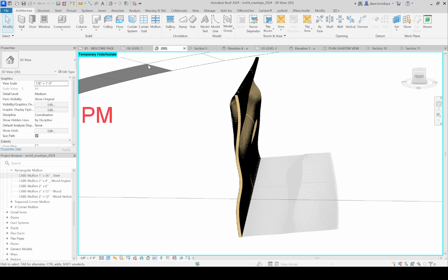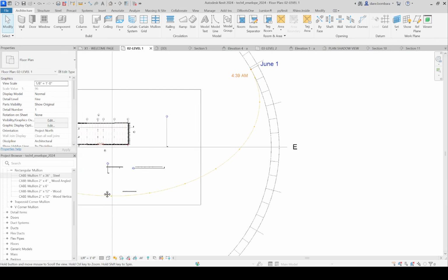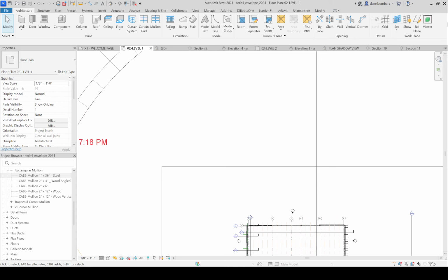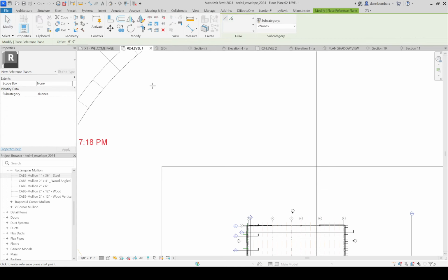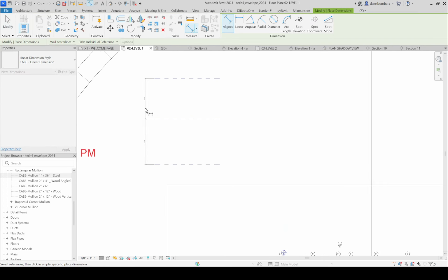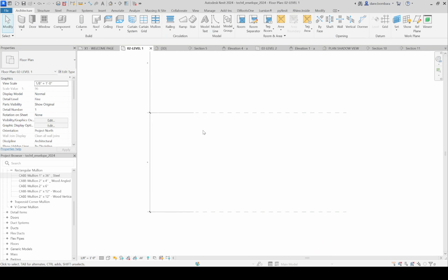So what I did here to make something like this is I'll do a very simplistic version. We talked a little bit about reference planes last week. I made some reference planes that I was going to draw on. In Rhino, when you want to loft something, you draw multiple curves, then you select those curves and you loft a shape across them. It's essentially what we're doing. So I'm creating the planes on which to draw.